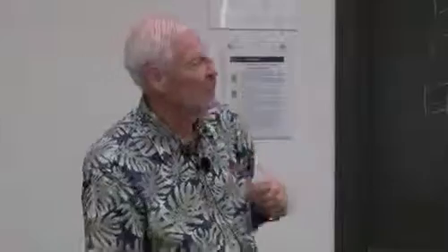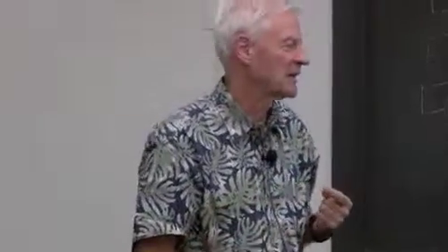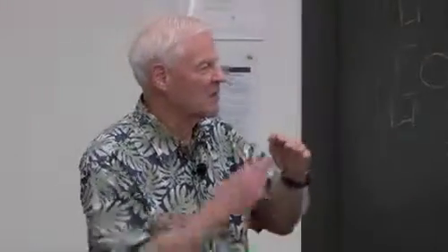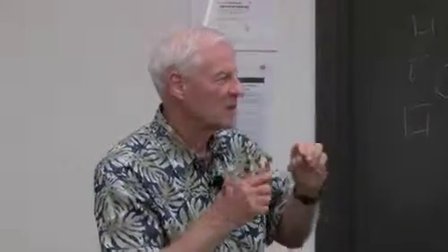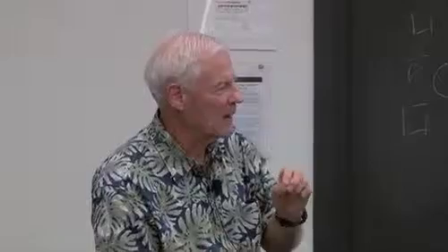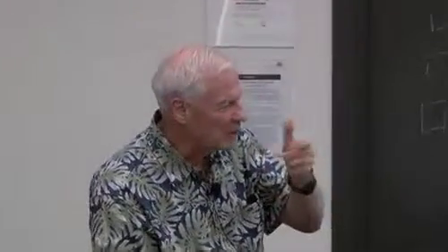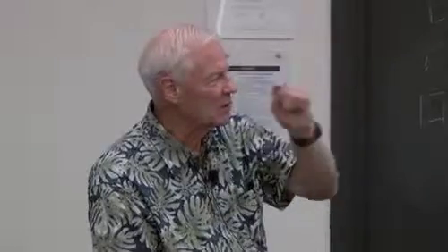On the other hand, if you want to measure the fuel-air ratio, now you can use toluene because it's inversely proportional. So problems are oftentimes opportunities. Toluene is strongly impacted by oxygen, so in many regimes, it's almost like the signal's proportional to toluene over oxygen.